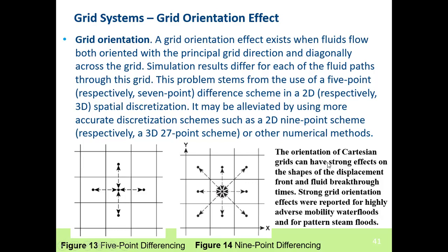That's why I said the orientation of Cartesian grids can have a strong effect on the shapes of the displacement front and breakthrough times. Strong grid orientation effects were reported for highly adverse mobility water floods and for pattern steam floods.